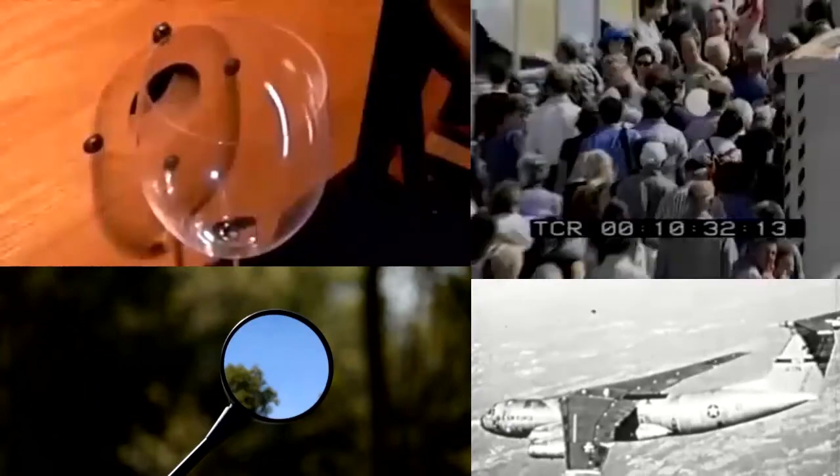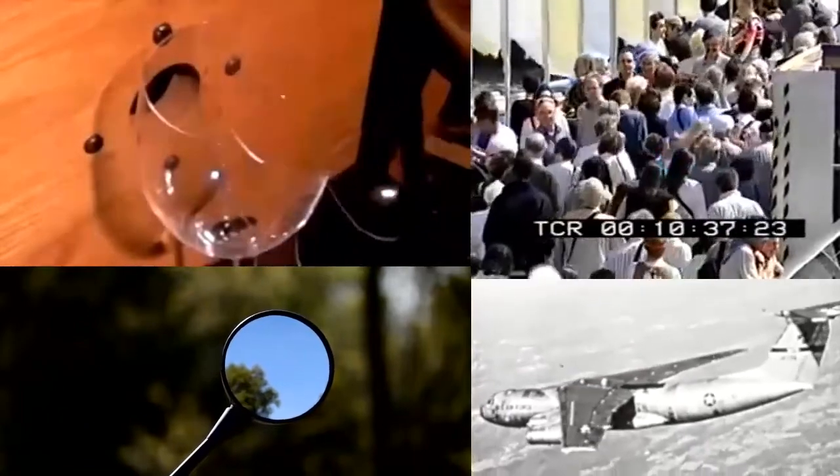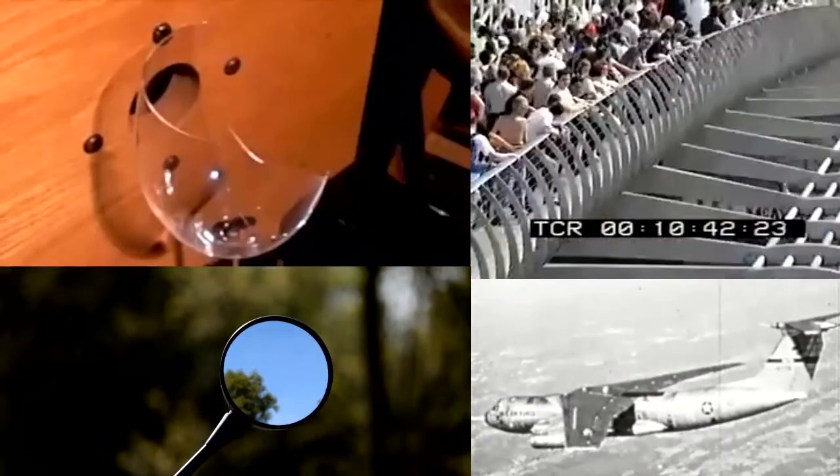What's happening to the glass, the bridge, the rear-view mirror and the aircraft is that the external loads are exciting a specific mode of the structure, making the response way higher than it should normally be. Modal analysis is a key tool to help understand and control these phenomena. In the rest of this session, we will try to clarify how it is possible to analyze and control these phenomena. But let's first take a look at the general reasons why modal analysis is important and what benefit it brings to the industry.